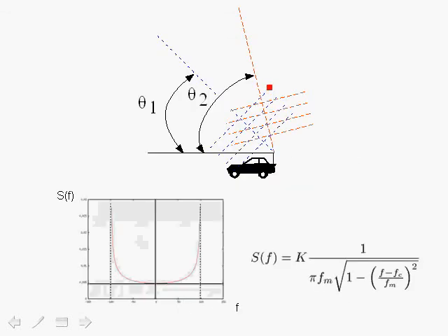If we take a good look at the situation that we encounter with a mobile moving in a dense urban environment and exhibiting Doppler shift, we noted that the vehicle's antenna receives plane waves from the transmitter at carrier frequency f sub c, arriving at different angles, and you have a large number of such plane waves arriving at the antenna and combining constructively and destructively. The signal at the receiver therefore can be modeled using the central limit theorem.